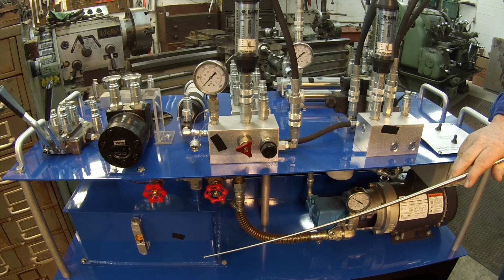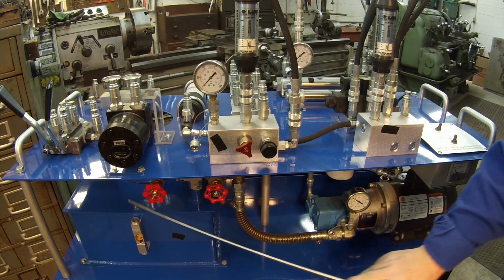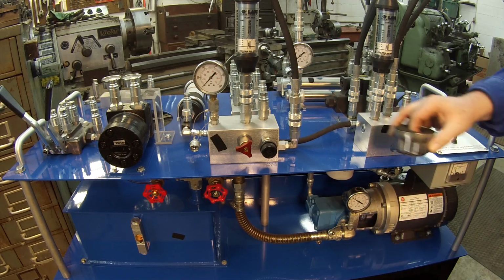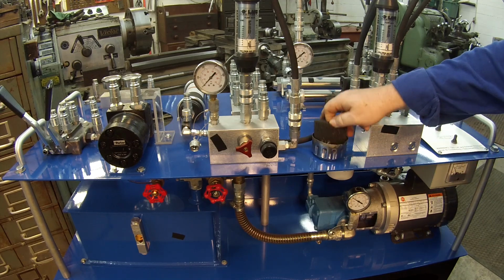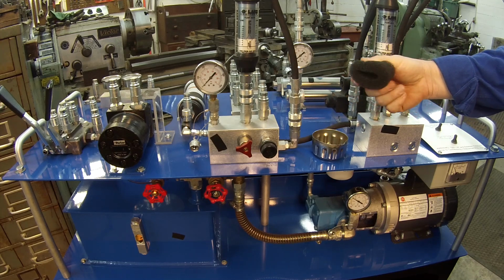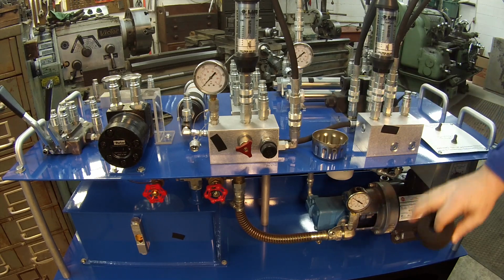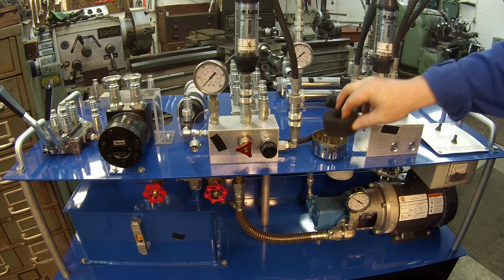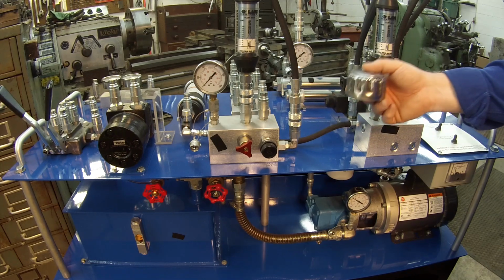Alright, how they fail is leaks, obviously, which is a safety hazard. Clogged breathers. There's a breather up here on top of the reservoir, and what I've got is one of these breathers actually taken apart so you can see the things that happen inside of that breather. This is just a piece of foam, so you'll see those breathers are basically garbage. They don't catch very much. The things that I need to protect this pump from are down in the 3 micron level, and this definitely isn't 3 microns. So if you see one of these silver breathers on top of your system, it basically isn't doing very much.